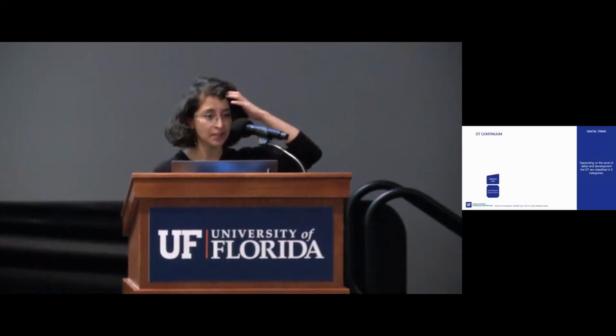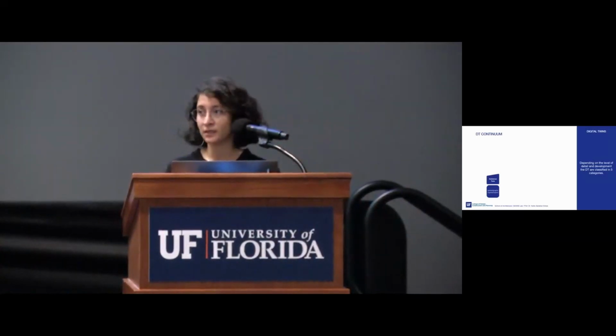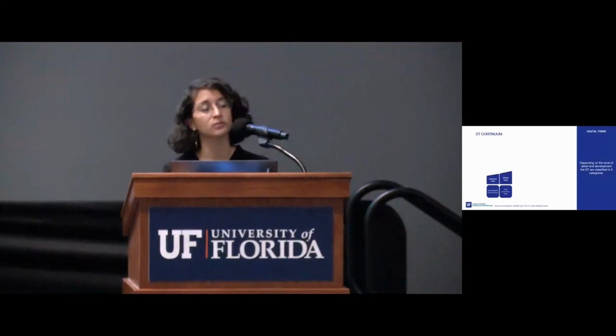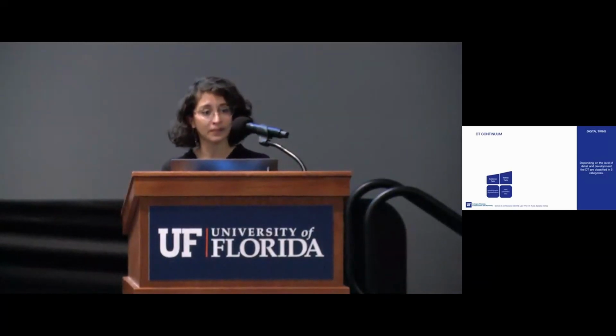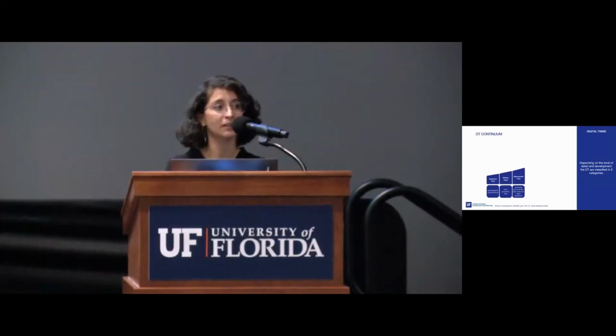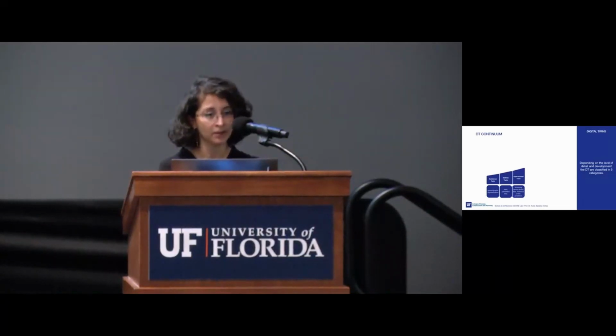So in digital twin, similar to BIM, you have different types of categories. So you have the first one, which is called existence twin, and this is similar to what you will get with a BIM level of 300, which is about spatial and graphic representations. You have the status digital twin. Here you are able to get static parametric data, so you're using some data that can be generated synthetically. Then you go to the operational digital twin, which is about connecting real-time data or getting the sensor in the environment directly connected with the virtual model that you have.